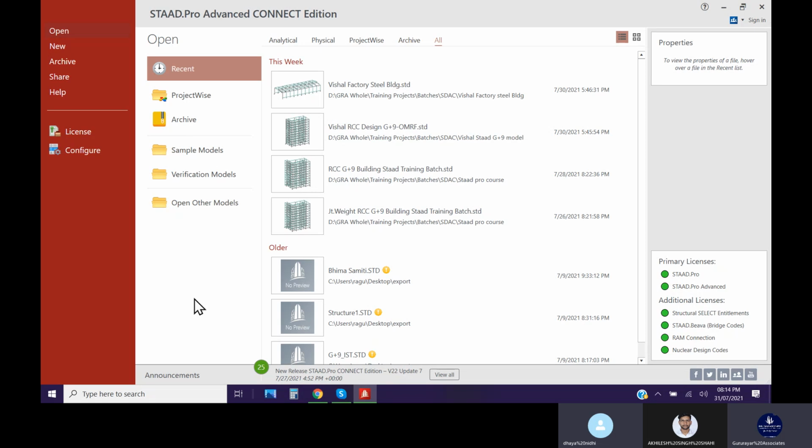So the decorative one won't take the load. Design wise, the weight of the decorative work we have to calculate approximately and then consider it over the beam or above the column, in axial way or maybe in flexural way or compressive way, whatever it may be. We have to calculate the decorative works approximately and include them in our design. The decorative one will not take load. It's just decorative only. Okay. I got it. Okay, sir.